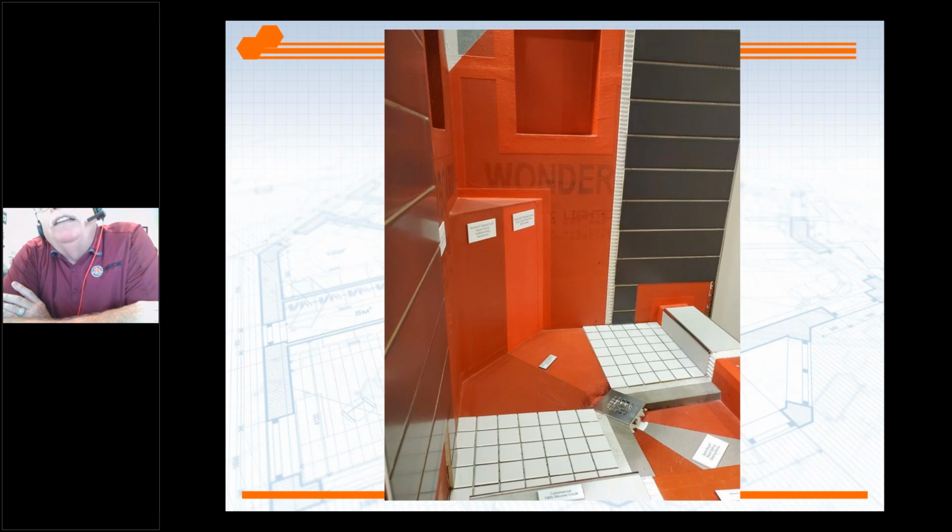There are a lot of details now where we can put the waterproofing directly on top of that mortar bed installation, directly underneath the tile, as you see on the right there. And that way it evaporates much quicker. You don't get the water being held in the mortar bed as with the traditional ones. So my recommendation is use the waterproofing on top of the mortar bed installations.